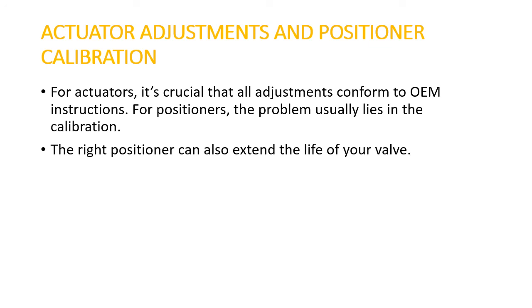There are also situations where the problem is found with the actuator, like the actuator diaphragm is passing, or the actuator diaphragm has been damaged, or the spring is damaged. All these situations arise. There is a lot of discussion that can be done about control valve maintenance and repair. I have only tabulated some very important and common problems and associated solutions.